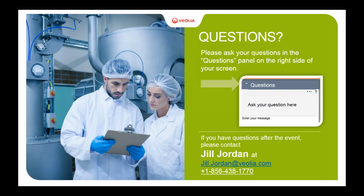Caustic freezes, what does it freeze at, Joe? 50% freezes at 55 Fahrenheit. So your caustic lines, unless you have a reactor and you're listening from maybe Miami or Key West, which I don't think we have any reactors down that far, your caustic line should be heat traced and insulated if it is outside, because obviously 55 Fahrenheit you're going to get all the time.